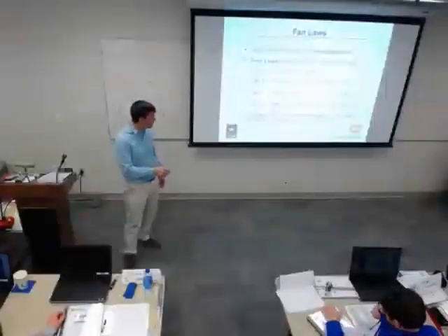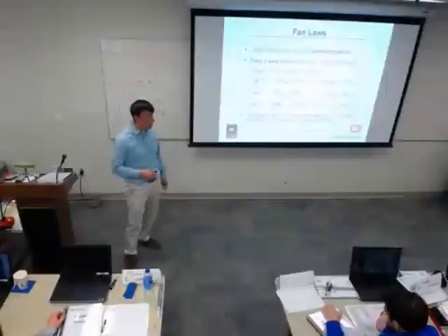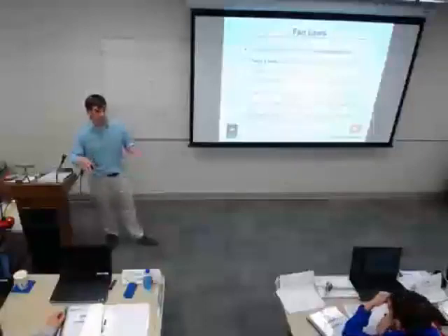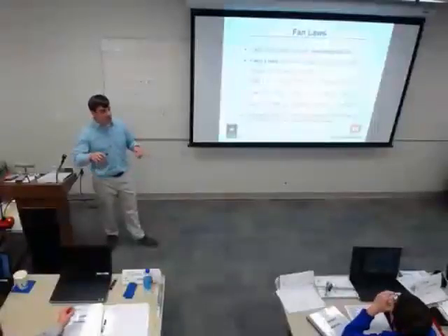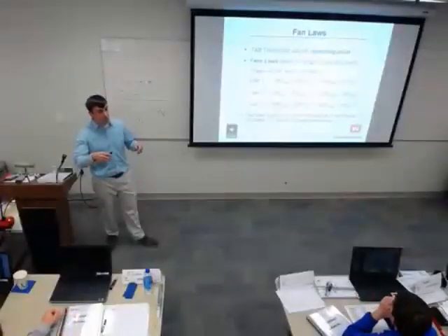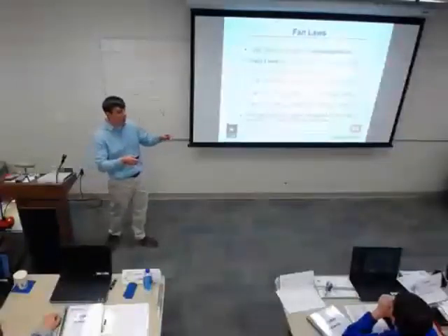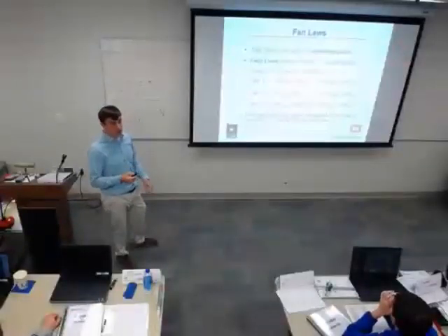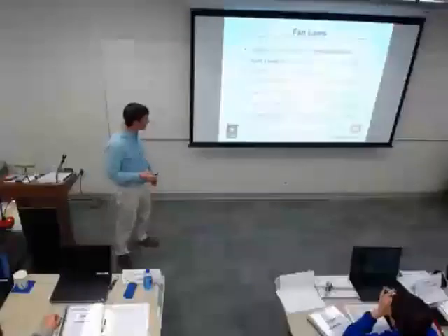Keep in mind, this only applies when resistance to airflow is constant, so my set duct configuration. If I start moving dampers, and I don't have the same system curve anymore, this only applies on one system curve, like I showed you on the fan curve.